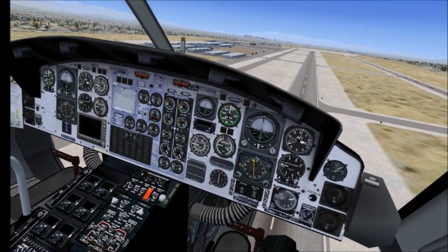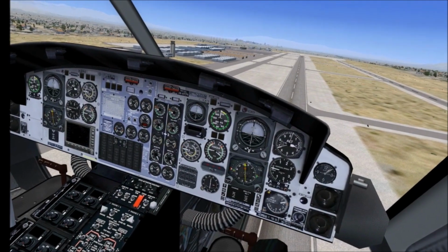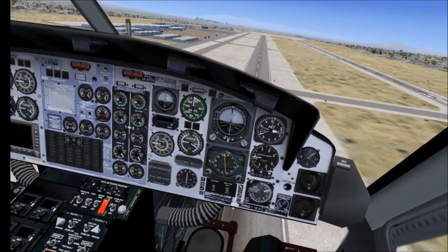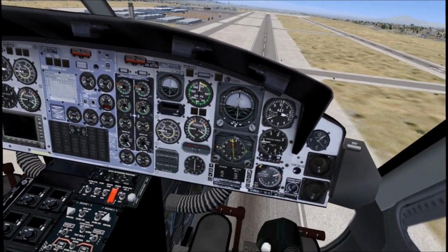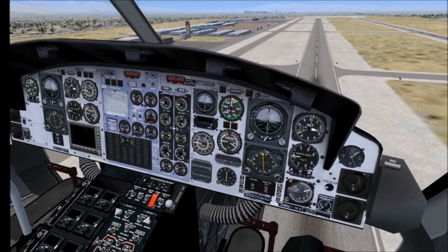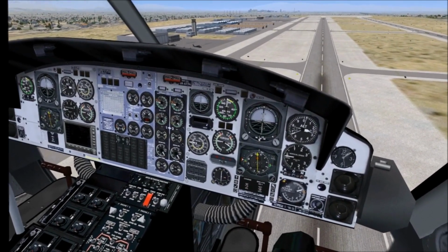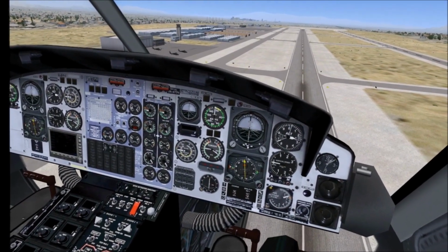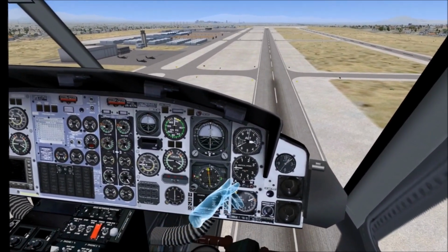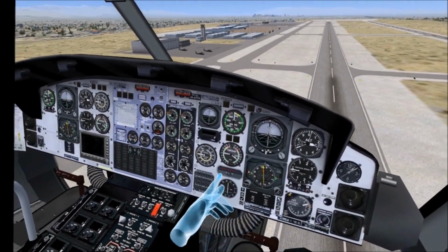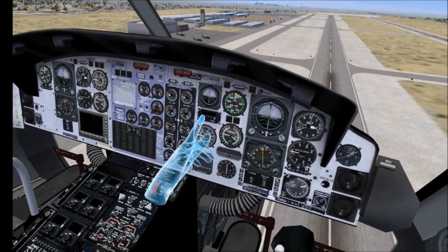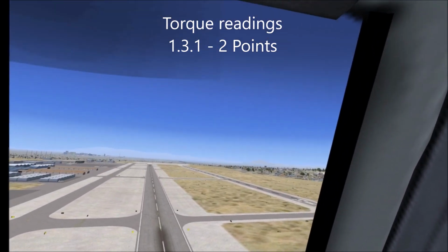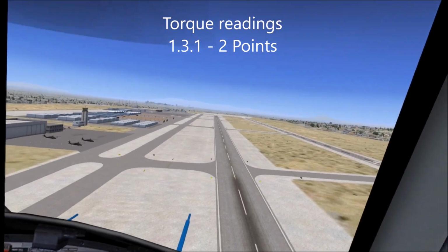All right, well, okay. So now, maybe that was my problem last time. Now the VSI is actually at 0. Oh no, we're looking pretty good here. So yeah, that's actually not too bad. So about an 8% increase in torque to maintain OGE hover. Yeah, I'll call that good. So VSI is at 0. We're OGE. We definitely got a torque increase. So yeah, we'll call that realistic. I'll take it. All right. So we'll give them 2 points for that.